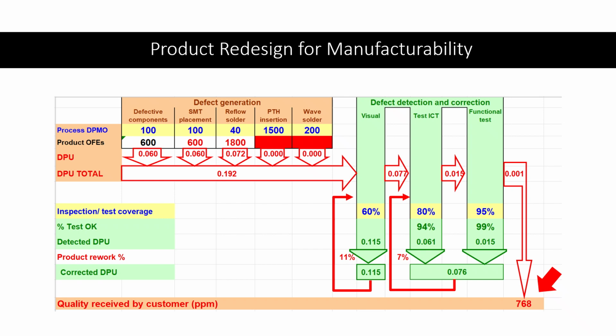When we try to reduce wave solder defects, for instance, we realize that there is, typically, a mix of component sizes on the board. When the board goes through the wave solder, typically at 250 degrees C, small components reach this temperature immediately, but large components take longer. This means that some components may be overheated, and others underheated, causing defects. We can find the optimal process parameters, solder temperature and conveyor speed, for each type of board with design of experiments.